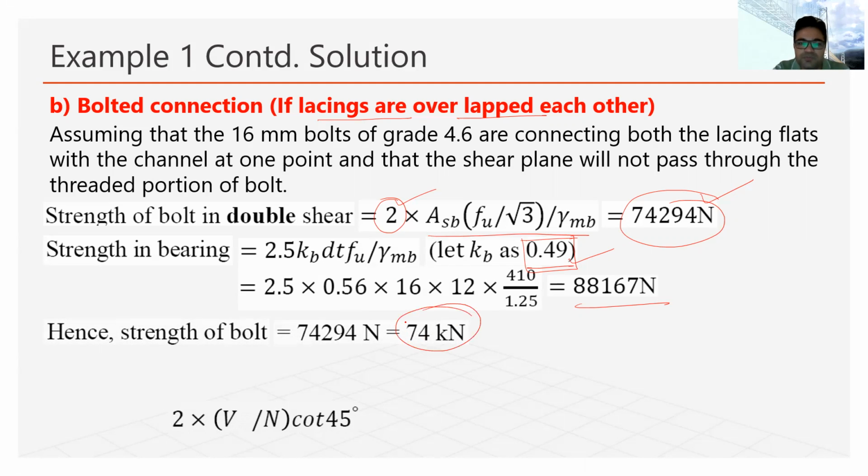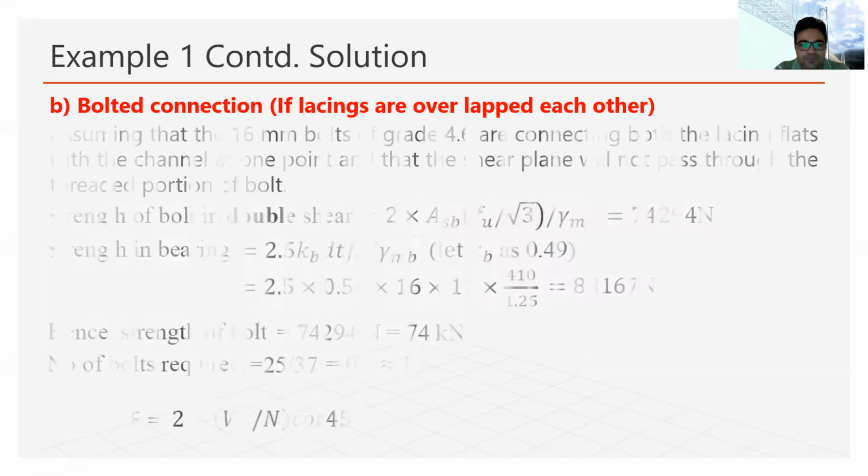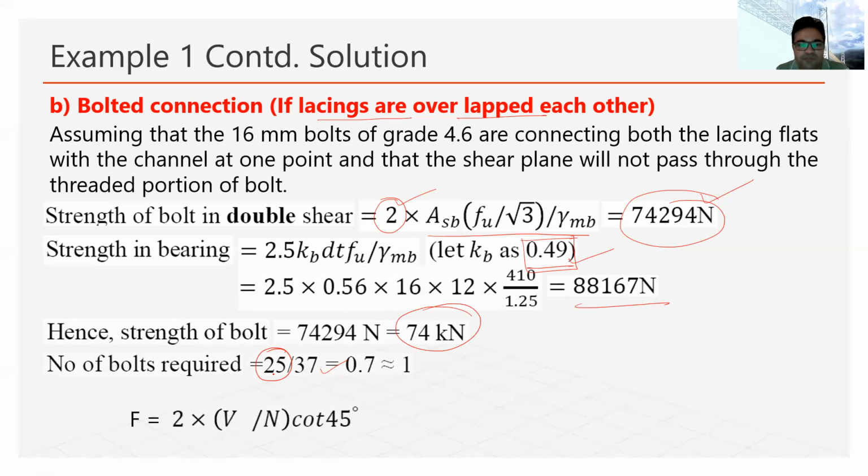And you know that the number of bolts required will be the force in the lacing bar divided by the strength of the bolt. This time we have calculated the resultant force. I hope you understand.